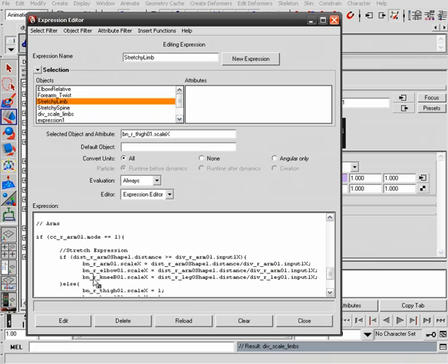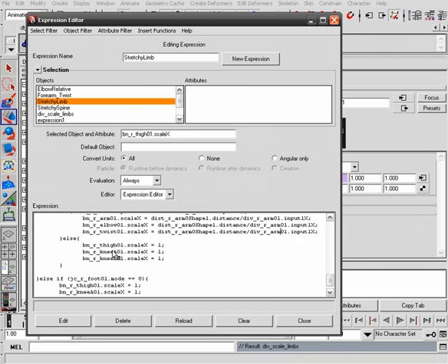For our next bone, we're actually going to apply our forearm twist. So that was just called twist. Simple as that. Switch leg to arm. Switch leg to arm. Okay, and we want to go through this slowly to make sure everything is going to be switched properly. So again, we need to switch our thigh to arm. Switch the knee to elbow. Careful not to get rid of the 0, 1. And switch this knee B to twist. Great, and we're just about done here.